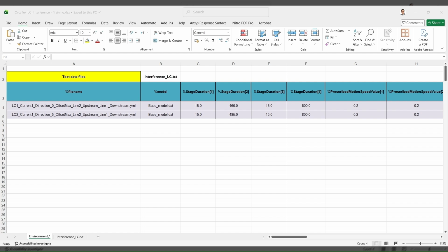Although OrcaFlex allows buoyancy to be modeled either as discrete buoyant clamps or as smeared properties over a line section, the discrete approach is required in this workflow to represent the real local hydrodynamic and structural discontinuities used for VIV assessment.